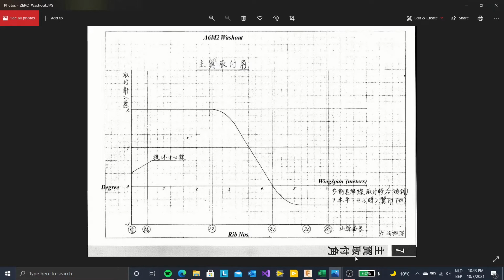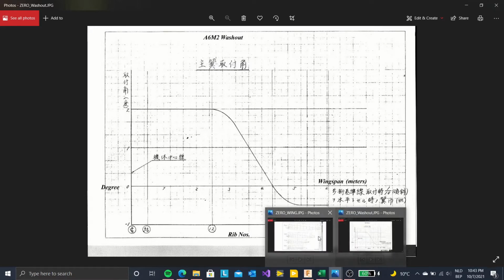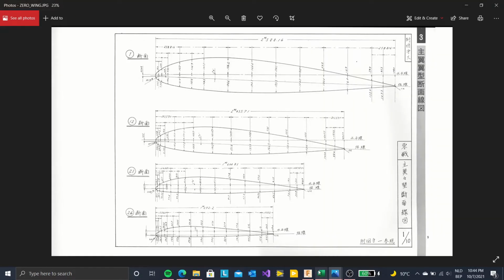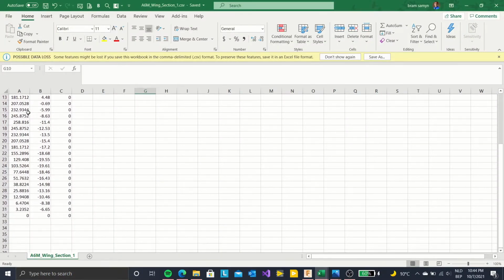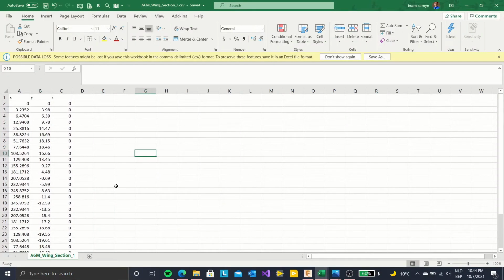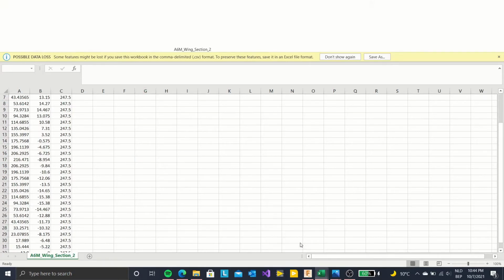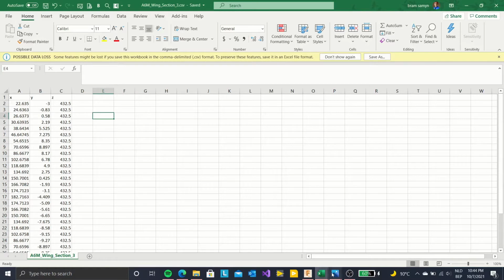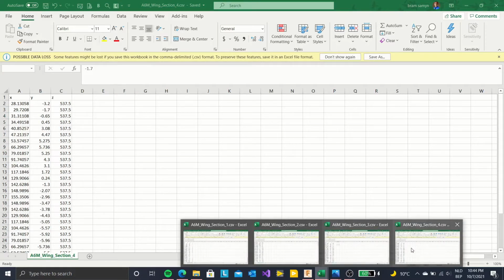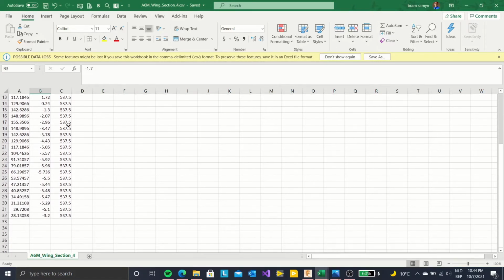With the sketches, we can create different Excel files to import into Fusion 360. As you can see, these are the 4 Excel files that were constructed from the dimensions given on the different drawings. As you will see, the airfoils will be pretty rough, but you can fix this by defining more points on your aerofoil. As I'm using coordinates from drawings where the designer already incorporated the inclination into the coordinate system, it won't be necessary to rotate the airfoil sections.